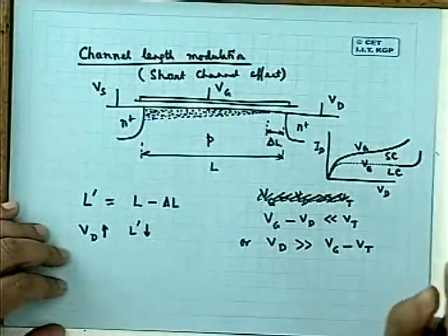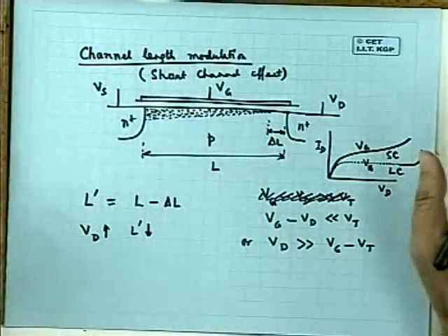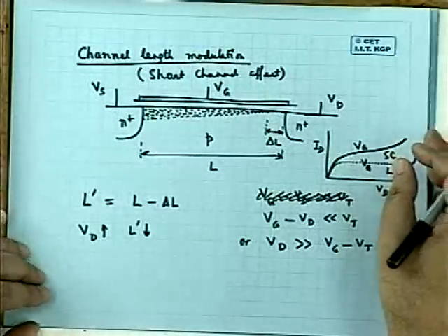is the most important thing for your MOSFET for circuit simulation purposes. It is affected by drain-induced barrier lowering, by the short channel charge sharing effect, and thirdly, by the channel length modulation effect. All of them combined influence the current-voltage characteristics of a MOSFET.